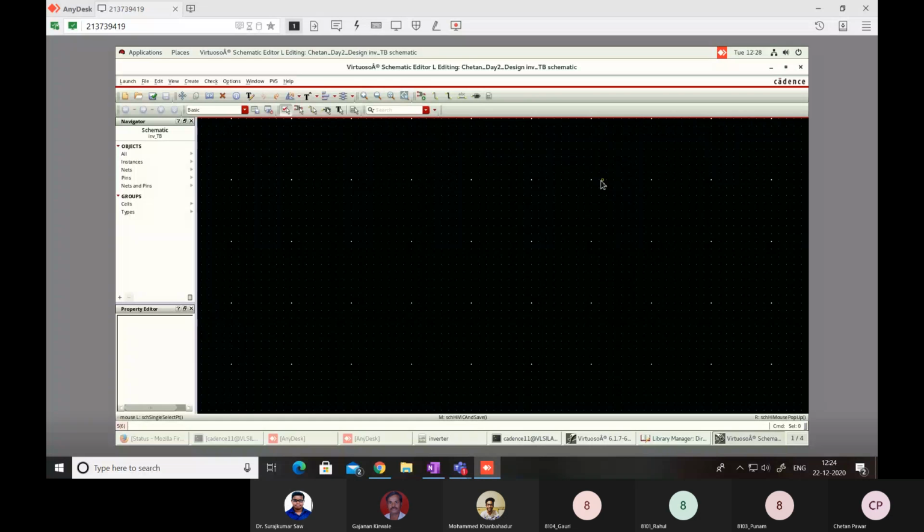Now go to file. Poonam, I'm giving this instruction to you. File, yes. New cell view. Okay. Now pop-up has occurred. Click on that pop-up. Or on the bottom one there is a window. Okay. Yes. Click there. Now inverter, what is the name there? Cell name? Sir, inverter, INV something. Underscore TB. You just put underscore TB after that.